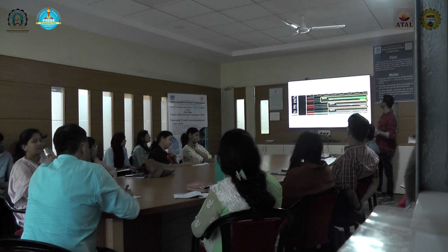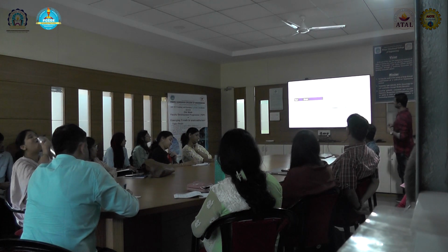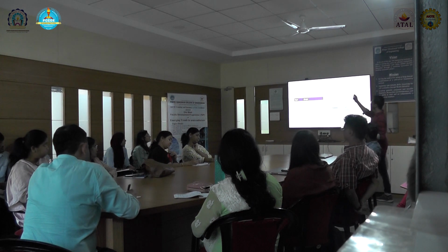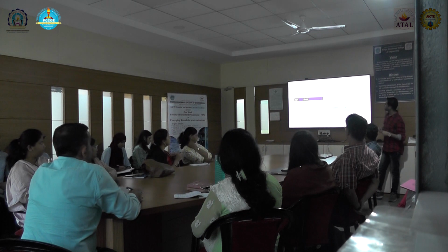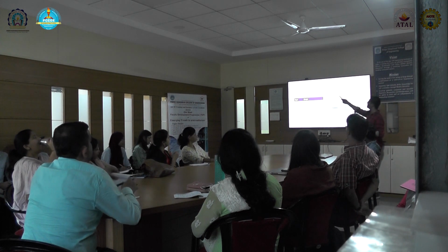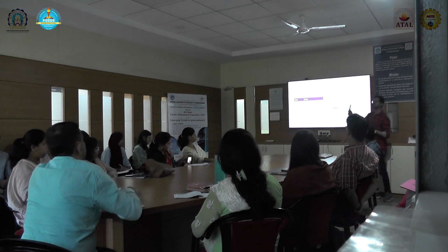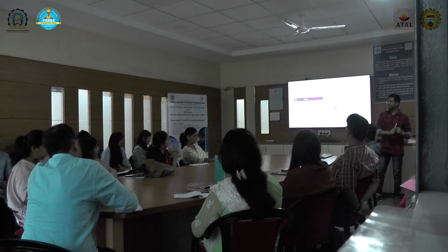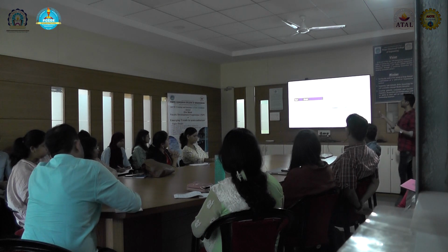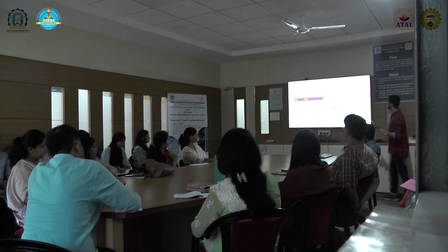So, summary. What is a property? A property is just a Boolean expression which is used by formal to define what we require. It can be of 3 types: assertion, assumption, and cover. Assertions are used to check the output. Assumptions are used to restrict the inputs from taking illegal values, and cover is used to find some specific scenario. And this is that simple.